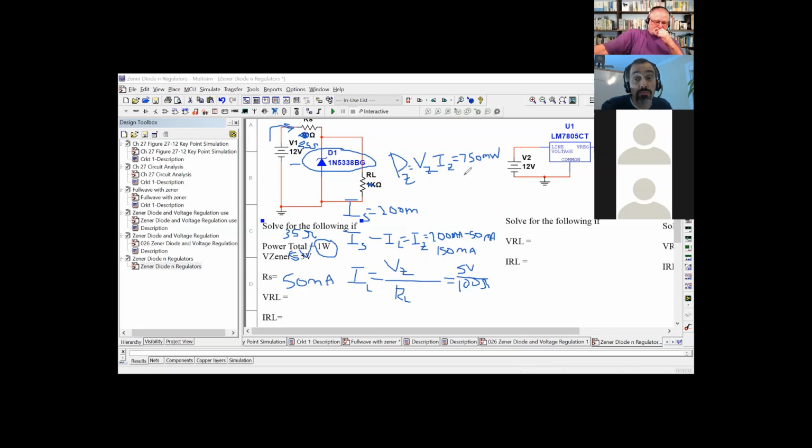If I was going to repair the circuit and I looked at these specs and said, okay, what kind of Zener do I need to get? I would be going with a 1.5 watt to 2 watt Zener, because we're at 0.75 and that's close to 1 watt. You never know what's going to happen to the circuit down the line. It could increase as things get older. We've seen this happen.